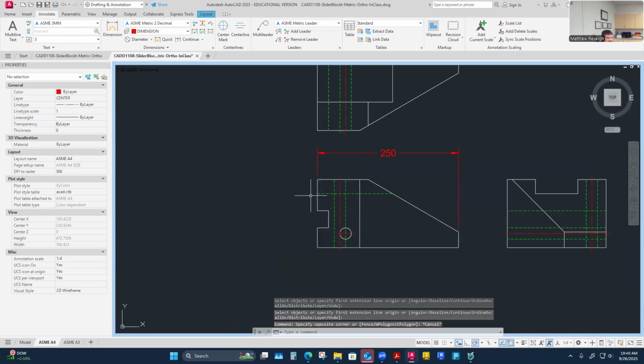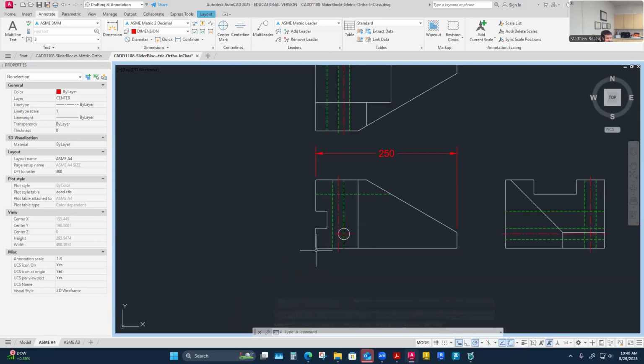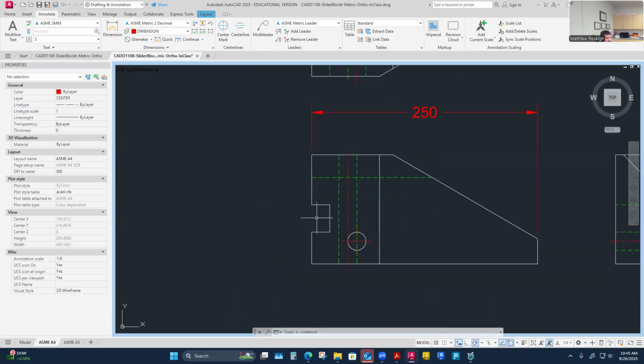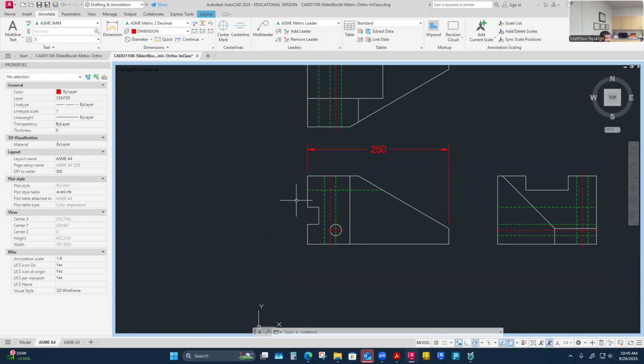The overall height, I can kind of already tell this is going to be outside here. And Riley just worked ahead a little bit, and he ended up wanting to detail the notch over here, and that is correct because I'm already looking at this notch saying the most visible features of this notch are really over on the left side of the front view. So I feel like that is where I'm actually bundling the dimensions for that. I know it breaks the rule, but if I want to dimension that in between views, I'm going to be pulling a lot of extension lines over and across my visible object. So it's just going to break up clarity. So for that reason, I break the rule and I say, I think I'll put the details on the notch over here. And so that's all going to be going on.